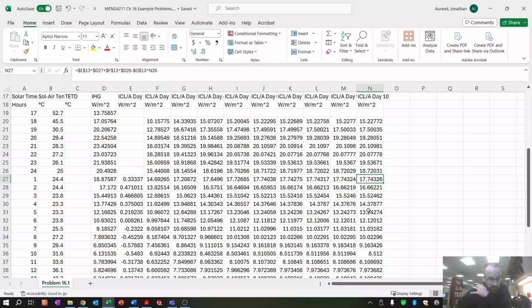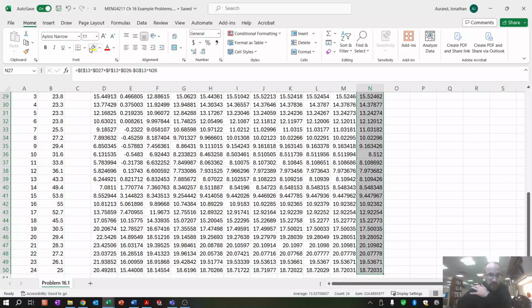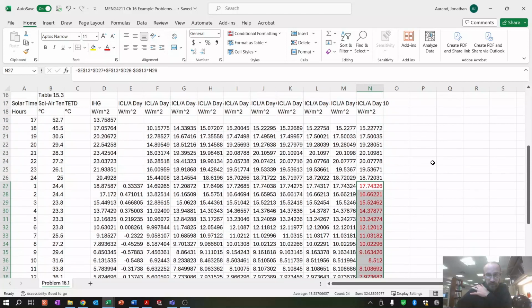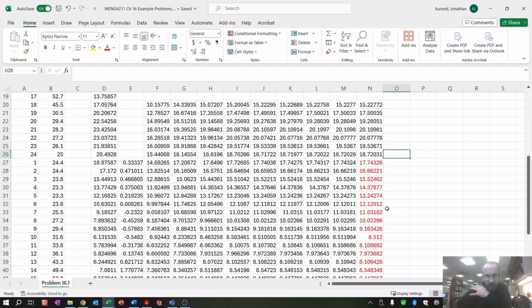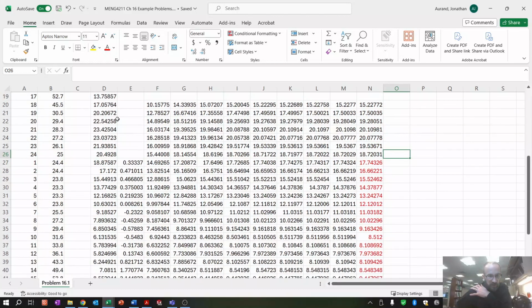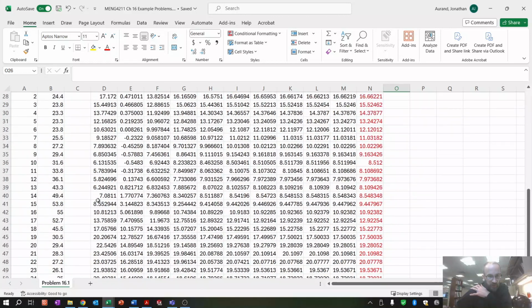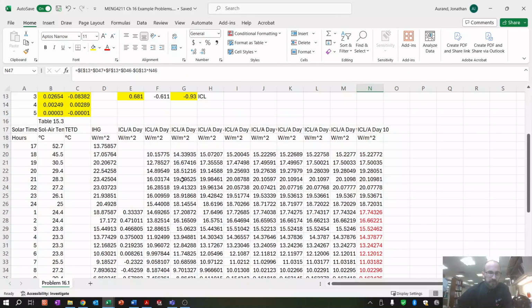So these guys would be my final values for instantaneous cooling load per area for that west facing wall throughout the day. So we're seeing that damping coming through, right? Our instantaneous heat gain was over here. Our cooling load, we're seeing damping on that a little bit. So like here's 13, a little less. So what do we have? A peak of 24 versus 20. So we're seeing that damping.